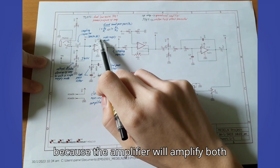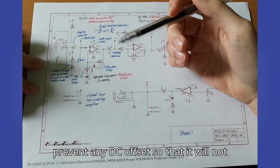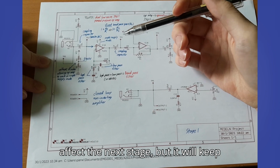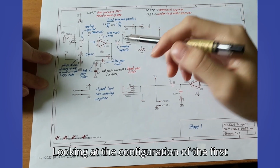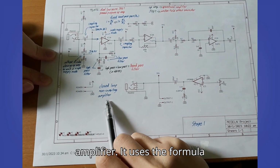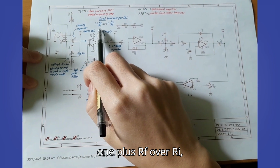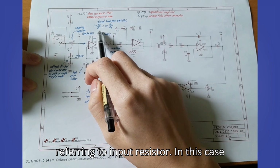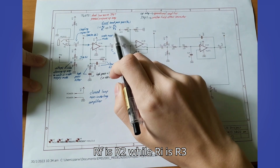Because the amplifier will amplify both AC and DC, C4 is needed to prevent any DC offset so that it will not affect the next stage, but it will keep amplified AC output. Looking at the configuration of the first stage, it is a closed-loop non-inverting amplifier. It uses the formula 1 plus RF over RI, F referring to feedback resistor while I referring to input resistor. In this case, RF is R2 while RI is R3.